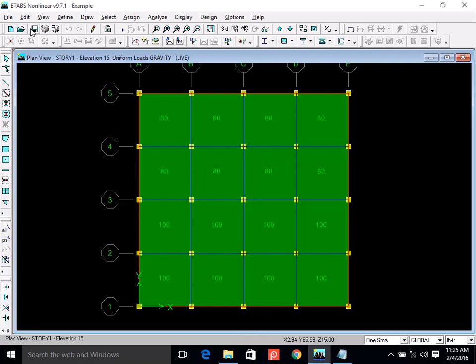You can do the math later on, and I strongly recommend that you verify this number. Okay, 9-inch thick, 1 foot high, and length is immaterial because I am talking about 1 foot. Okay, 9-inch by 1 foot. I mean, this is 9-inch wall. Up to this point, 1 foot. The load is 90 pounds per foot.